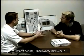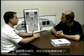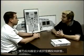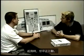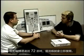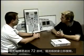Let's say same scenario, but you forgot to arm the spoilers. I'd have to get both of them in idle and at least one of the thrust reversers in at least idle reverse. On takeoff, you abort the start. When would you get spoiler deployment? With a wheel speed of 72 knots, I'd get a spoiler deployment immediately.